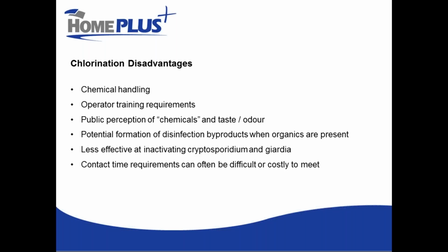Disadvantages, it's a little more complicated to operate. We're going to be handling some chemicals. There are some negative public perceptions of chemicals and taste and odor, and we can help you deal with some of those things, of course. We do have the potential for formation of disinfection byproducts when organics are present, so we have to monitor and be careful about that. And sometimes our contact time requirements can be a little troublesome to meet, especially in small systems where space might be a high priority or not available for us.